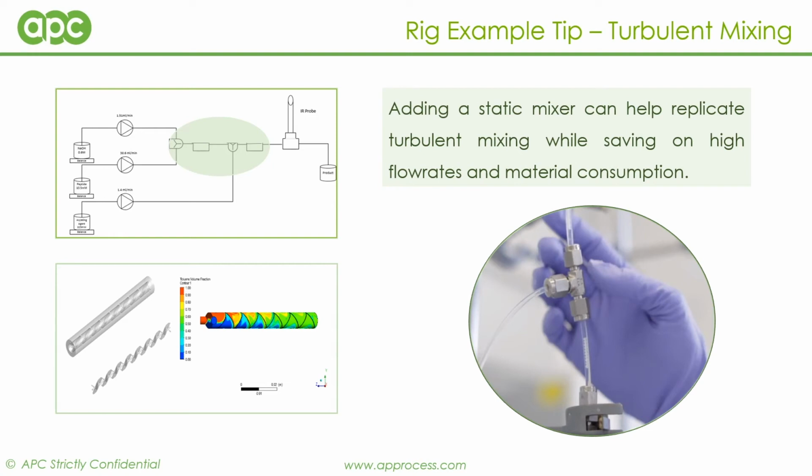A simple solution could be implemented to overcome the laminar mixing in the lab scale model. One such way of overcoming this is to include a small static mixer like the one in the photo here. These static mixers are available from a number of off-the-shelf vendors, and they're quite inexpensive. Due to the scale that's often incurred with these sort of lab models, severe material restrictions apply.